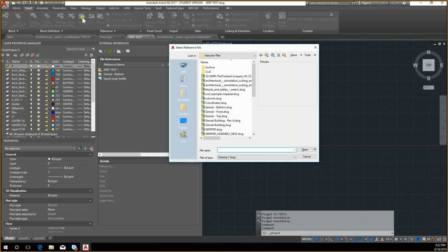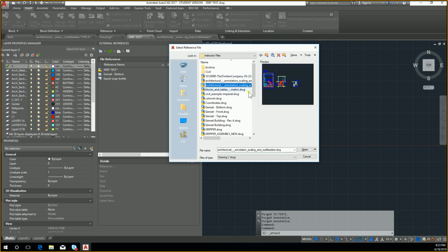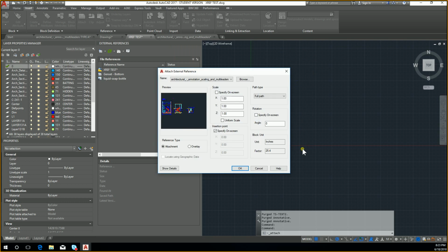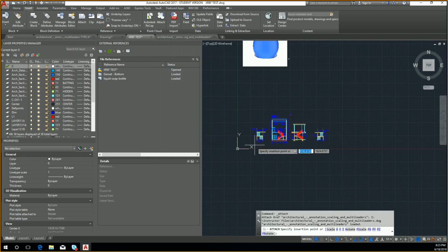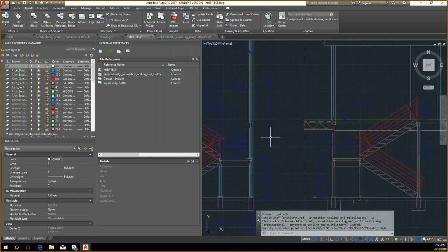You can't, again, this is sort of where AutoCAD has a little safety built in, because if you are switching back between inserting and attaching the same file, it does warn you. As you saw there, I have to purge away the block so that it does not get confused of what you're trying to do. So I've purged away the block now, so now I should be able to attach this again. Yep, like so. So now this is my attachment.